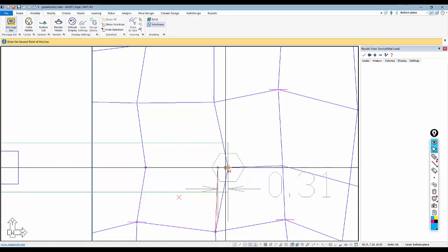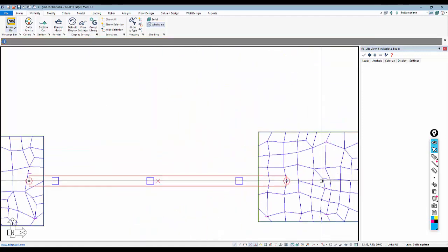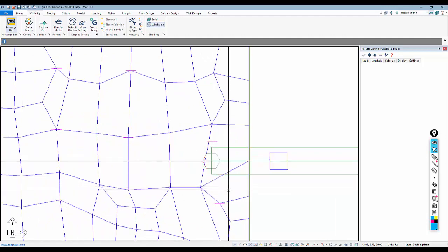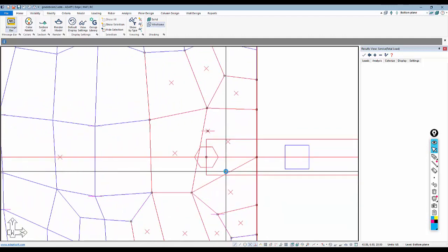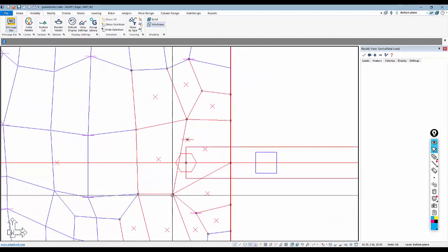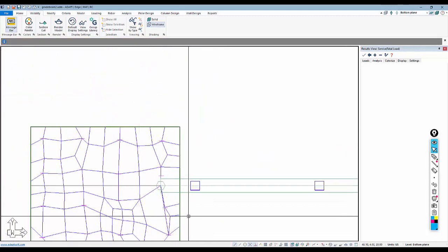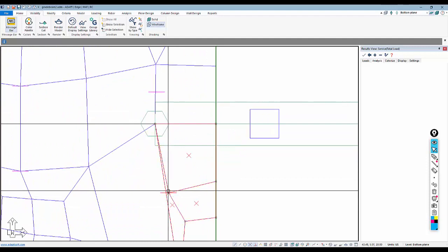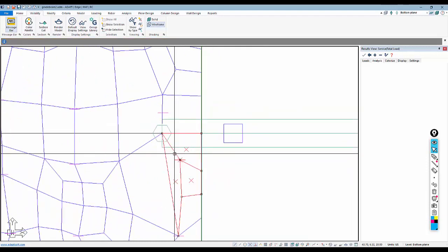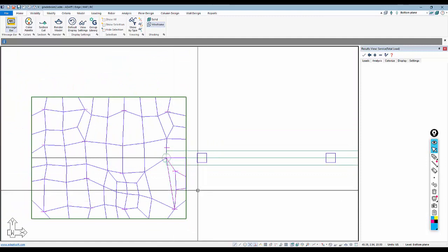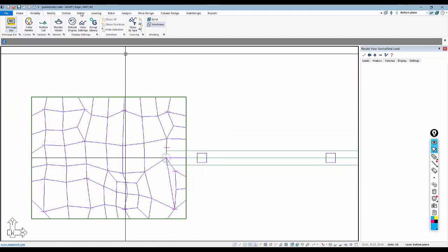And these are, again, just manual modifications to the mesh at this level, making sure we have proper connectivity of those elements. So this one I'm actually going to move down to this point. We have something going on there. This is kind of an elongated element there. We may want to mesh this at a tighter spacing.